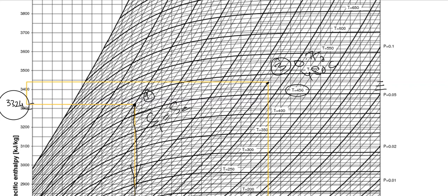Now at point 3, 0.7 megapascal, 480 degrees centigrade, if you check it, it would be, for example, 3400, 3450. So I can simply say 3440 something. It can be a value near 3440. So we have solved another point. So state number 1 to 2, then from 2 to 3, and then dropping in the second stage of the turbine from 3 to 4.